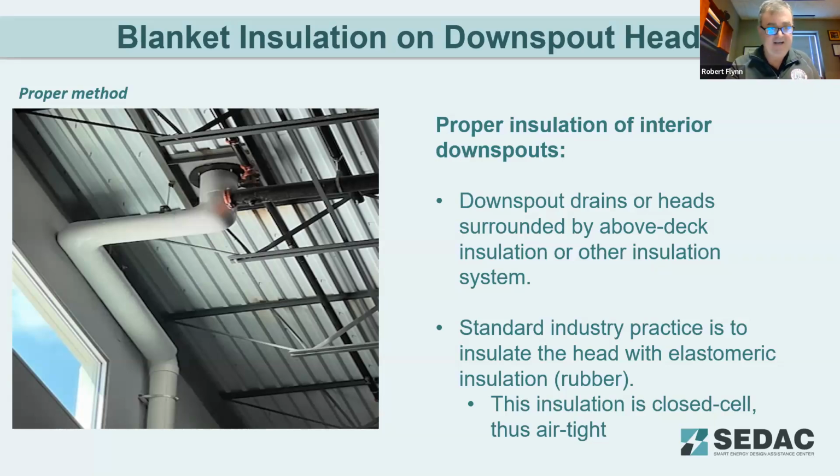However, once again, the hanger was buried, and as you can see, as we go down towards the vertical drop, they stopped at the first 90. Many specs will actually say on a commercial job that you'd have to do the horizontal all the way to the first 90, including the first 90 going down.